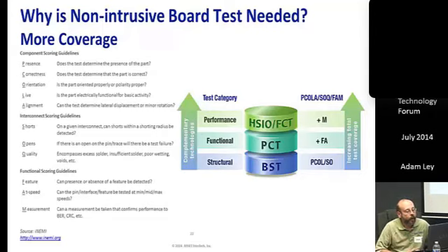For example, one of the things that we've done quite a bit at ASSET is system marginality validation, particularly based on Intel silicon. They implement a methodology that they call interconnect built-in self-test, which is an embedded instrumentation methodology accessible through JTAG that provides for physical layer testing by way of JTAG-controlled pseudorandom bit streams and, on the receive end, pattern checking.